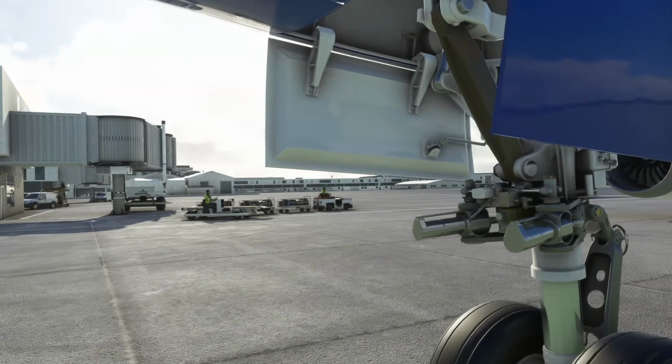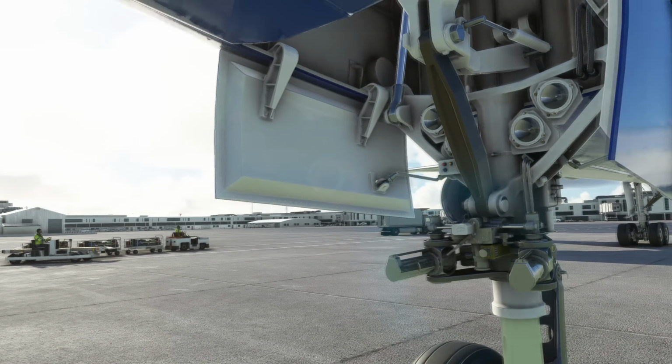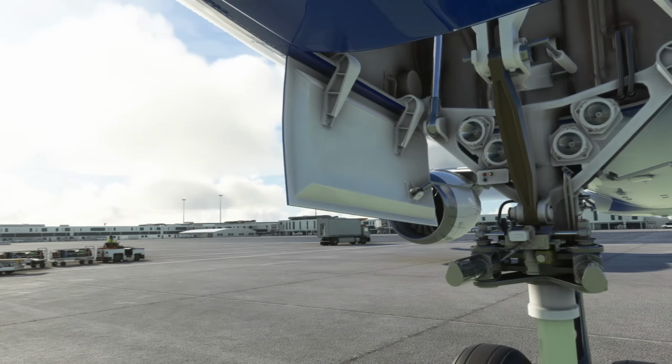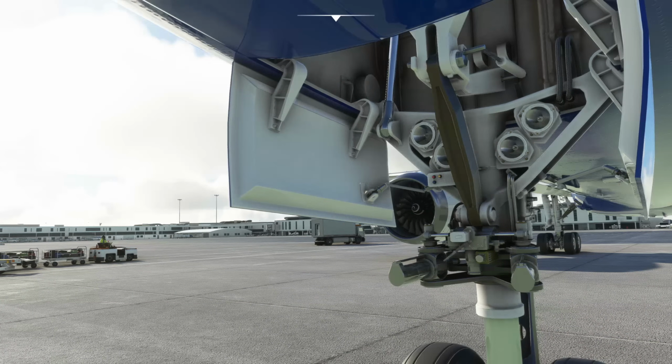And what you've got, if we can get around to them, is takeoff lights and taxi lights. The taxi lights will be on obviously for taxi, and the takeoff light is typically only actually used for landing. It's not really a takeoff light, and that's what it was on the Airbus. Yeah, there's a landing light on the nose gear, but it's only really used for landing. But we have the taxi lights as well.